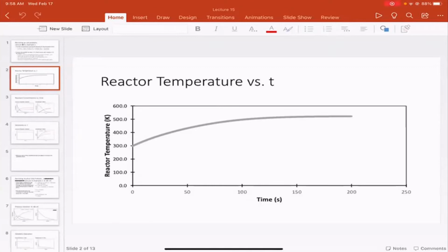That is our jacket temperature. And you're going to notice this when you solve non-isothermal reactor problems with a jacket. Eventually, most processes just lead to the jacket temperature. That's really the point of the jacket. Yes, you're going to add heat or remove heat, that's really great, but what you're trying to do in the jacket is set the temperature.